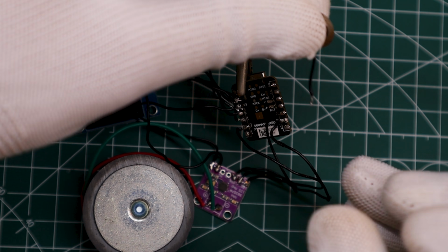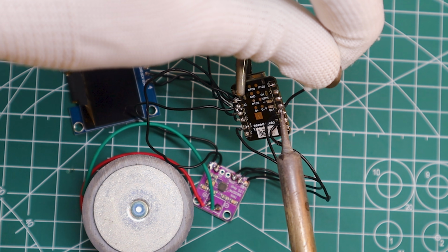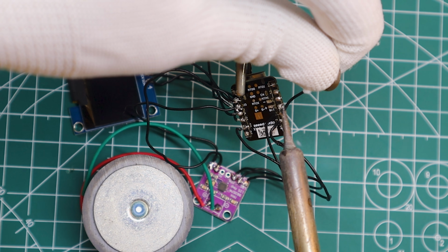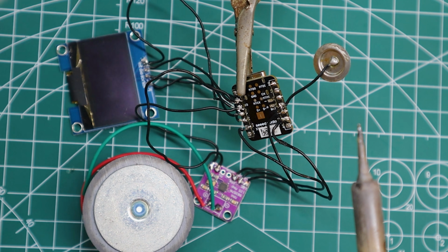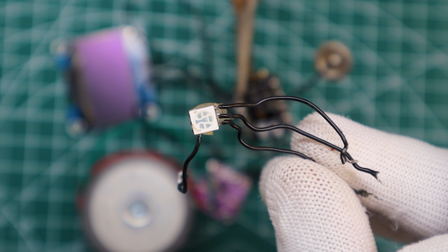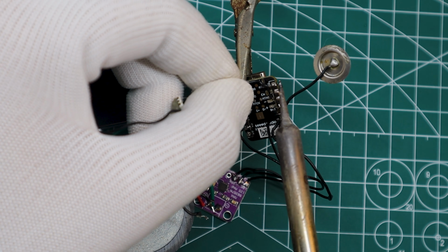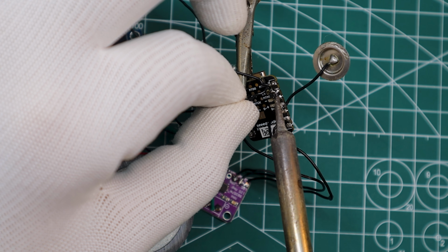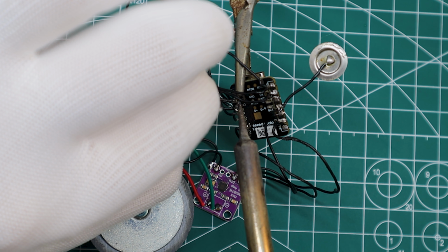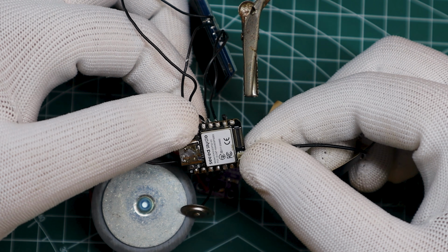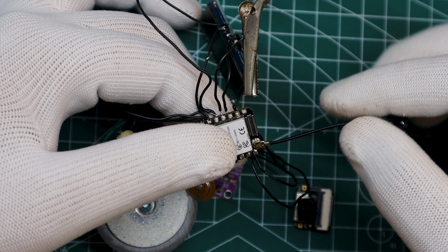Next, we will connect the touchpad to the ESP32. We have soldered a wire to the metal touchpad surface and that wire is connected to GPIO 4 of the ESP32. Now coming to the RGB LED connections, the red goes to GPIO 2, the green goes to GPIO 1, the blue pin goes to GPIO 3 and GND goes to GND on ESP32. After that, we simply connect the antenna to the ESP32 module.